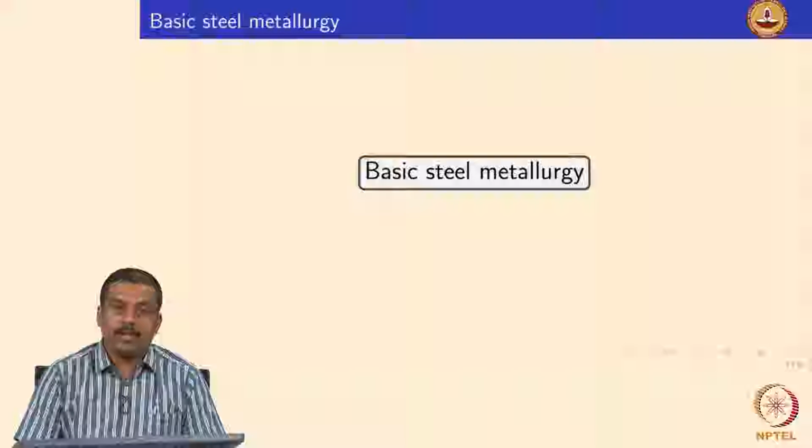and other alloying elements which are added to improve various mechanical performances, like niobium, titanium, vanadium. These are all micro alloying additions to cause precipitates, or some special alloying elements. Sometimes we even add boron. Apart from these alloying elements, we also have impurities. Generally, phosphorus and sulfur are considered impurities. It's very difficult to remove them, so we have to work with them. Even if they are there in a trace amount, they may still cause various problems during welding.